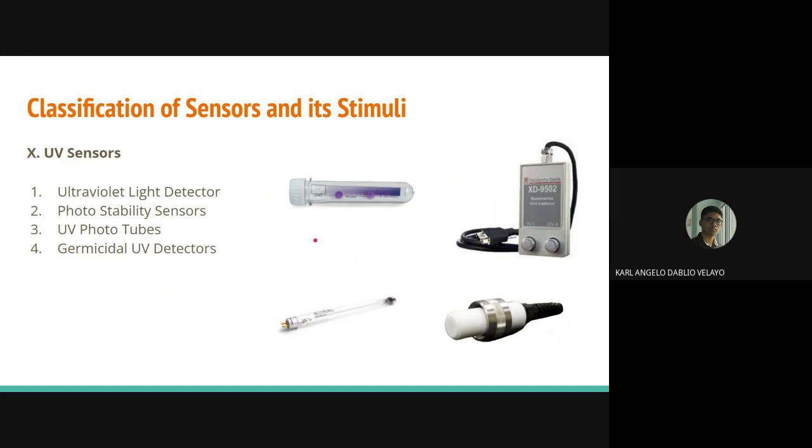It has a flashlight, but nonetheless, UV light detectors are a group of non-destructive chromatography detectors that measure the amount of ultraviolet or visible light that is absorbed by components of a mixture being eluted off the chromatography column. They are commonly used in pharmaceutical, biotech, and oil and gas industries.